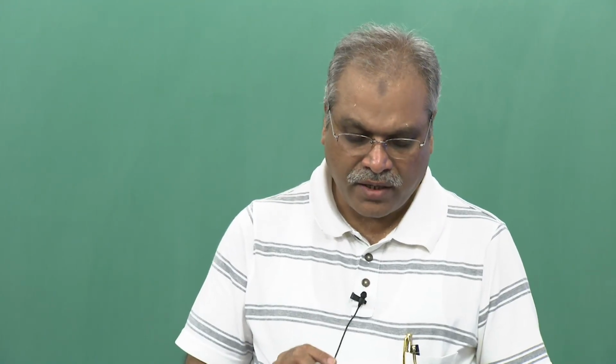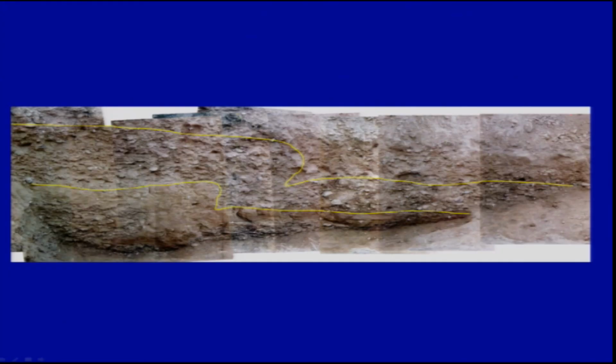Now this is an example from the Himalayas where we dug a very young fault along which we found the deformation. This is again an example of a monocline. Only one bed is dipping, while the other is almost horizontal. You can see the young deposits here which have been marked. These are gravels, and here we have a soil; one limb is dipping and another is almost horizontal.